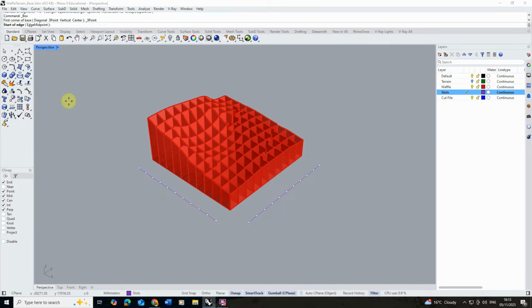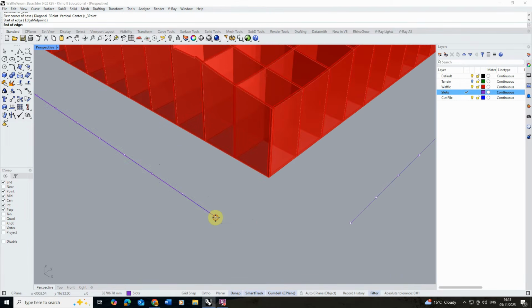So I'm going to start with this point here, and I'm going to draw out my box. But instead of just doing it 5mm, which is the width of my card, I'm going to do it a little bit wider. The reason for this is whenever we're making physical models, we want to give a little bit of tolerance to the things we make. It's good to make these shapes a little bit bigger than we need to, so when the pieces slot in, we know they fit. If we make it too tight, we're going to have to recut them by hand, and it takes a long time.